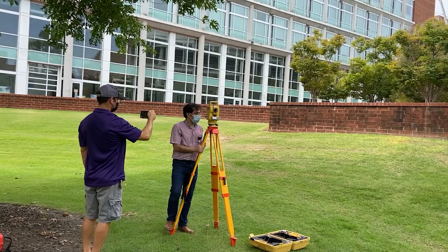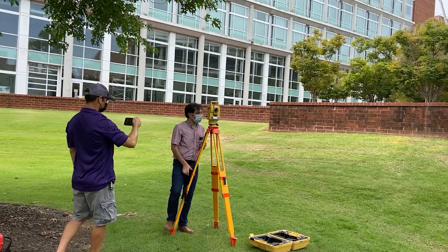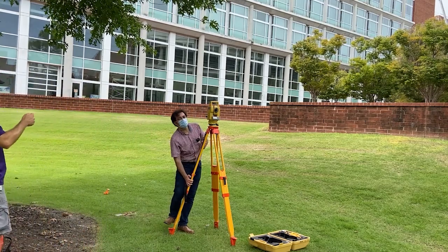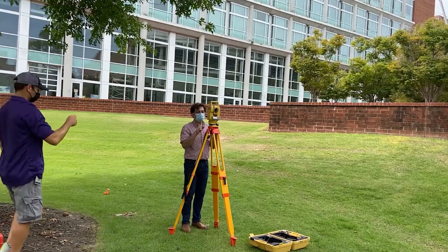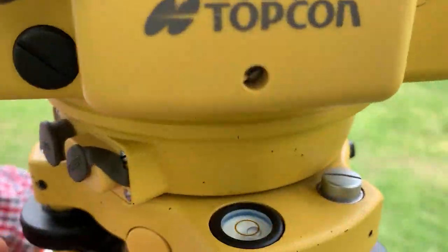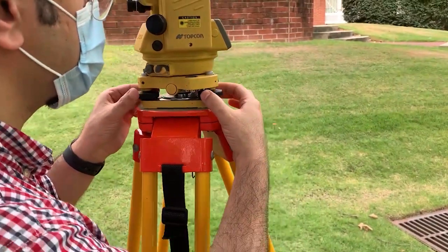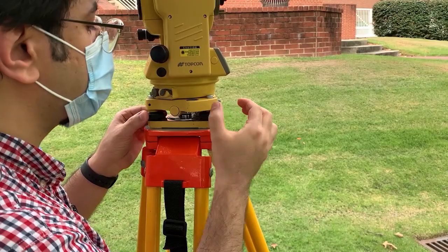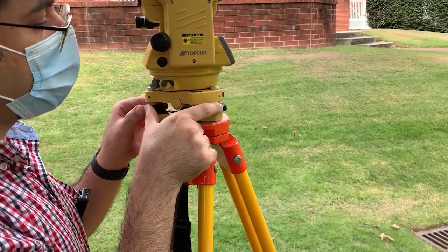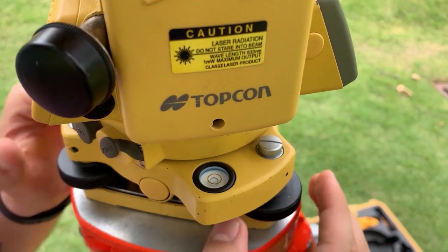I bring this down until the bubble is somehow inside the inner circle, then that's the stage that you can grab these knobs. So I grab these 2, rotate inside or outside until it is halfway between these 2. Not close to each of these, but the same distance.